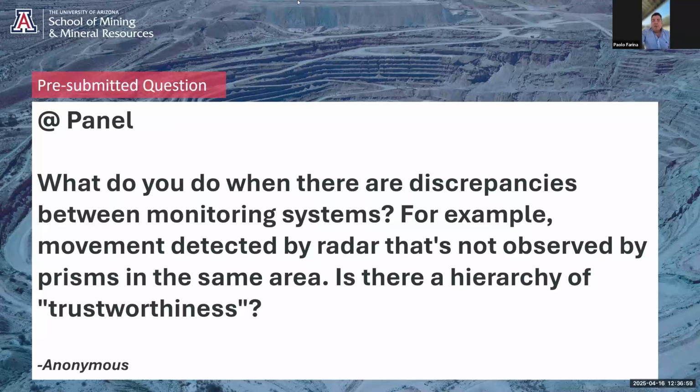Radar can have strong problems with the atmosphere, or with the atmospheric correction being too strong, because the algorithm does not fit the spatial pattern of the formation, or because the stable areas are not really stable. So I think we always have to put the different technologies together on the table and not trust any of them too much, but be critical, trying to understand what I'm supposed to see, and then see what you see in the different data. So that's my suggestion, my recommendation.